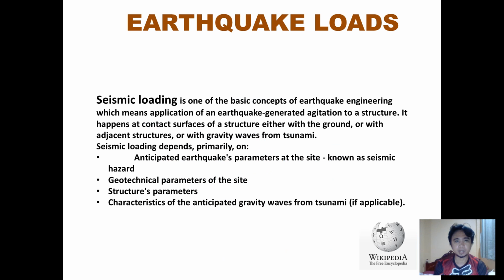So, another type of load is the earthquake load. Of course, it is normally termed seismic loading. Seismic loading is one of the basic concepts of earthquake engineering, which means applications of earthquake-generated agitation. How would a structure behave when there is ground shaking? This seismic loading will be converted into a lateral force that is applied on the frame of a certain building structure.